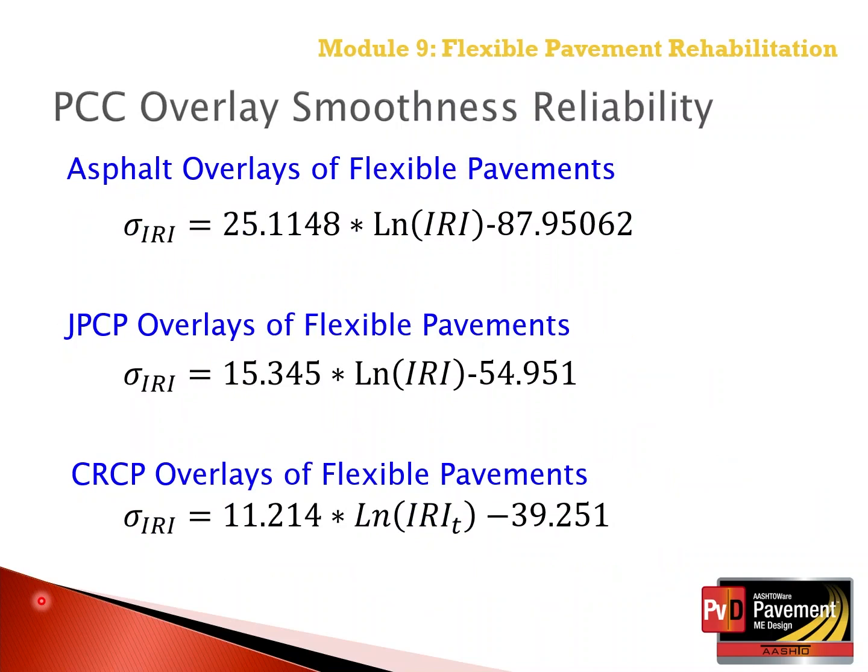Reliability, as we've noted in previous modules, was discussed in detail in Module 3 and how it is applied in the Pavement ME design software. The standard deviations of the residuals for the asphalt, JPCP, and CRCP overlays of flexible pavement smoothness are displayed on this slide. The standard deviation of the residuals is used to determine the reliability as related to smoothness of overlays of flexible pavements.